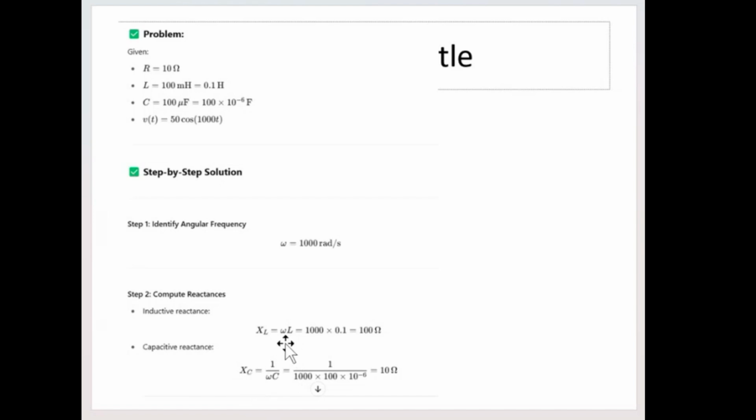From there, we want to calculate the value for the inductance and also the capacitance. In the phasor format, it would be omega L, and for the impedance part of that, it would be this times j. If we are talking impedances, this would be times j, and for the capacitor, this needs to be divided by j.